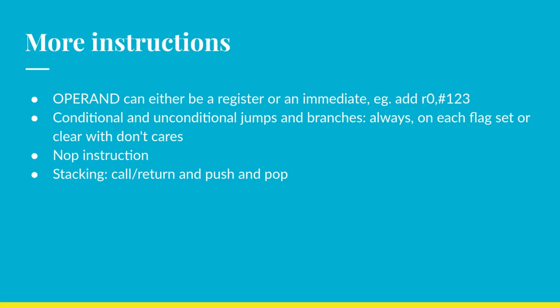We have a hardware stack, so you can call a subroutine which pushes on the current program counter, and then return, which will pull off the program counter for the last subroutine, and push and pop, which work pretty much how you would expect them to if you've done any assembly programming.